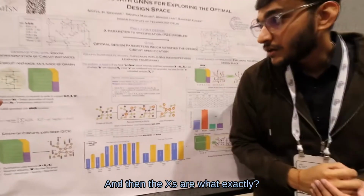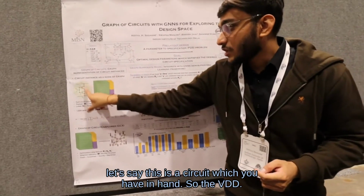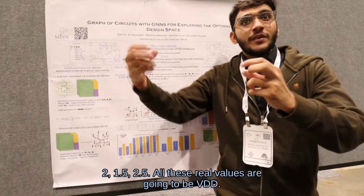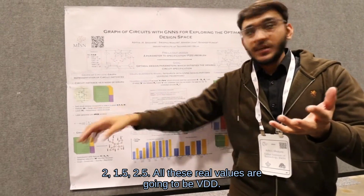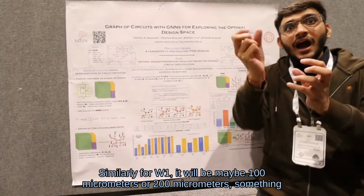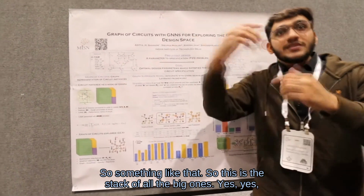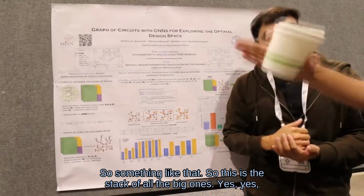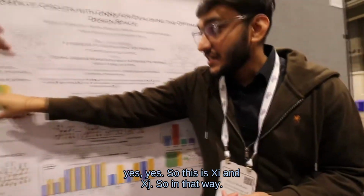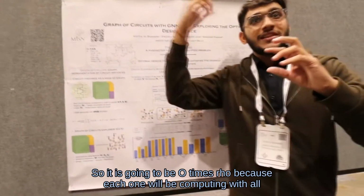And then the X's are what exactly? Feature vectors, that is the design matrix. As I mentioned, let's say this is a circuit which you have in hand. VDD can go to 1, 2, 1.5, 2.5. All these real values are going to be VDD. So these will contribute to different instances. Similarly, for W1, it will be maybe 100 micrometers or 200 micrometers, something like that. So that will be another row. So it's the stack of all of those. Yes. The i and the j are going to be different instantiations of this circuit, Xi and Xj. So in that way, it is going to be O(N squared) times.